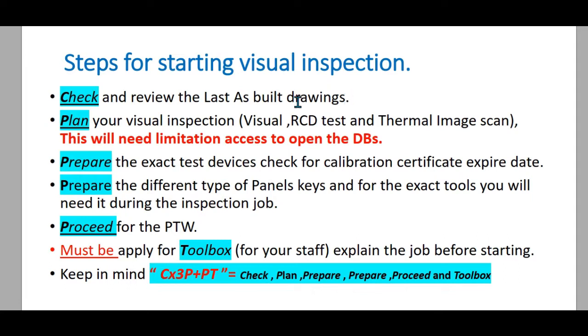So whatever the action, whether visual only, visual with RCD test, or visual with RCD and thermal image, we need special limited access to open the DBs according to the permit to work requirements.